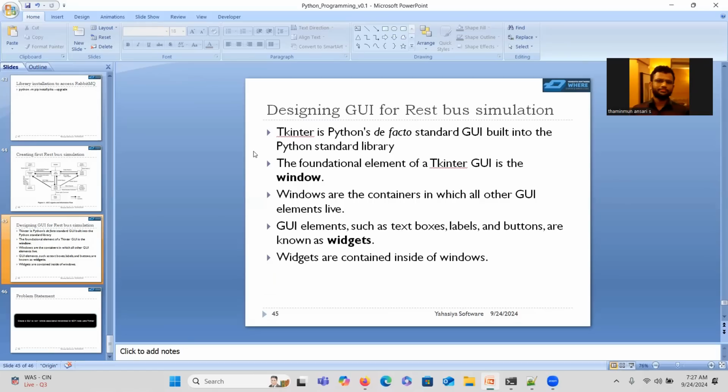But when it comes to REST simulation, people require some sort of user interface to interact with the CAN signals that are transmitted by different software nodes. For example, in BCM, we have vehicle speed, which is transmitted periodically right now. So there should be a user interface using which we have access to change the vehicle speed. How do we design such a thing in Python?